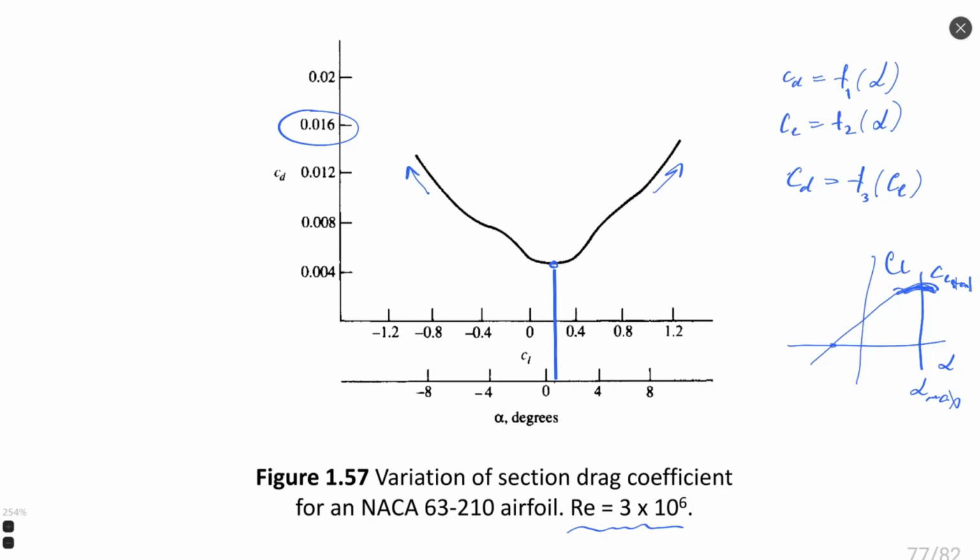You remember we just recently saw for a flat plate it was 2, so 2 is somewhere here. It's 100 times bigger, right? Or even 0.6 somewhere here is many times, tens of times, around 30 times bigger than the typical value for an airfoil. This is a significant difference. Only at these values of drag coefficient can we have sustained flight. So drag coefficient for an aerodynamic body is supposed to be small.